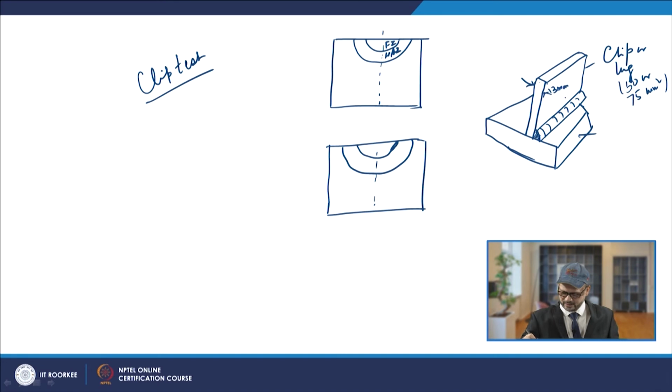Now, you will do the welding in normal conditions, and then allow this weld to cool to room temperature. Then you try to break it by hammering. So, suppose you have this specimen.